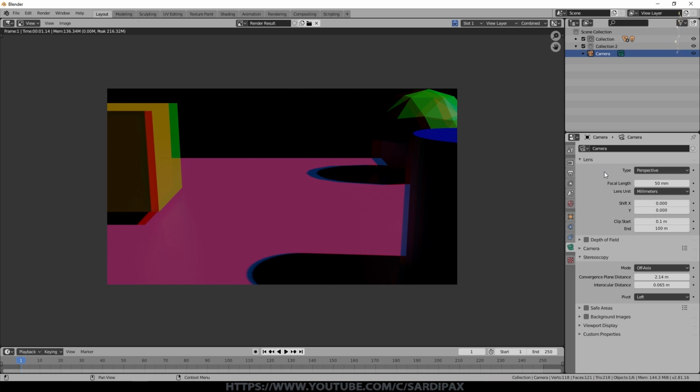but there's quite a bit of maths needed for that because you need to distort the images and so on. And another thing I'm considering is whether or not you could do it using reflective spheres and essentially just record the images as they're seen on reflective spheres. And again, there's a mapping exercise to do to turn that into a proper 2D image. There's some things I'm looking into there, and maybe I'll be able to come up with a method for producing 360 and 3D videos in Blender using the Eevee engine. But hopefully, in the not too distant future, we'll have a proper panoramic camera available in Eevee.